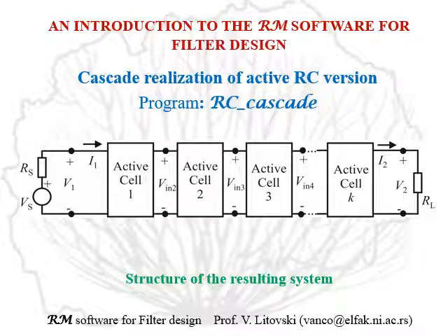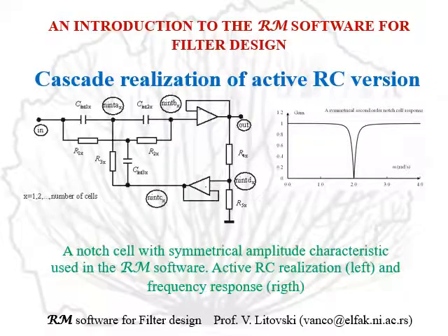And simply what is done mathematically when creating a transfer function as a product of biquads, here the same is transposed directly, and the gain is a product of the gains of the cells. A wide variety of cells has to be developed for such a program to be effective.